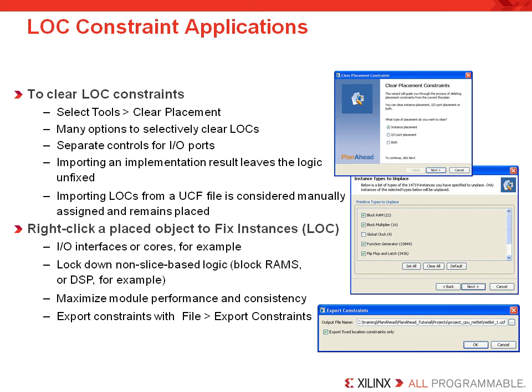The tool has a concept of fixed versus unfixed logic. You will want to place some objects, like IOs and block RAMs, onto these LOCs and they are considered fixed. For analyzing place and route timing, it is useful to see where the implementation tools place these objects. For the tools to do this, their placements must be unfixed. Before exporting the placement for an implementation run or to your UCF, the tool will ask if you want a LOC constraint in the UCF for all gates or just the user-placed fixed logic.